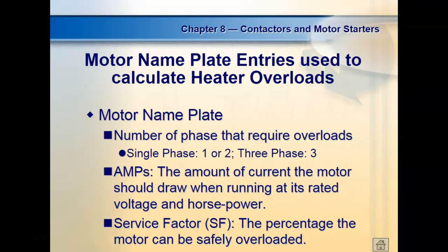Amps, it's not going to be the starting amps. That's going to be the running amps, if it's running its rated horsepower. So ours, if we put an ammeter on it and measured it, it says it's going to pull a certain amount of current at 208. Ours will be a lot less than that because we're not running at its rated horsepower, right?